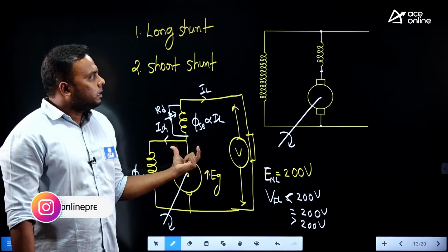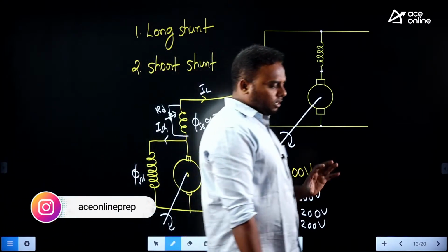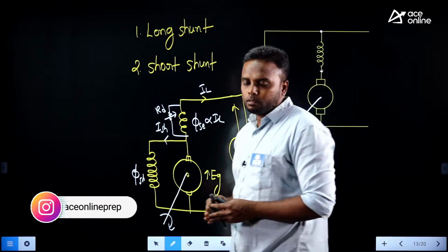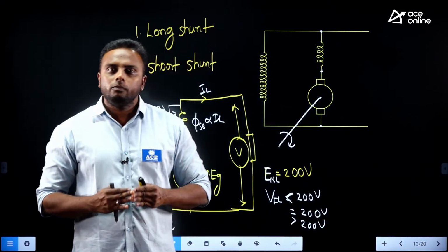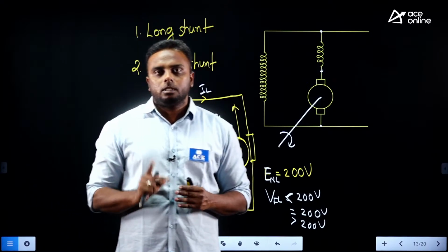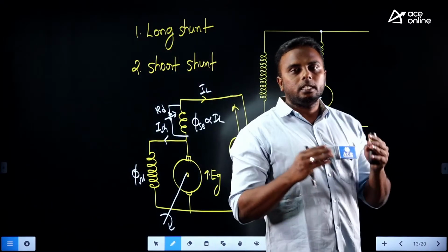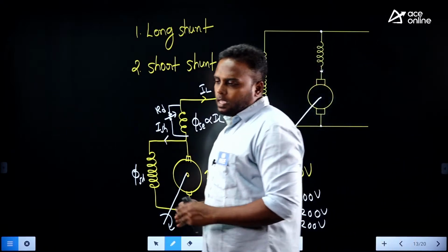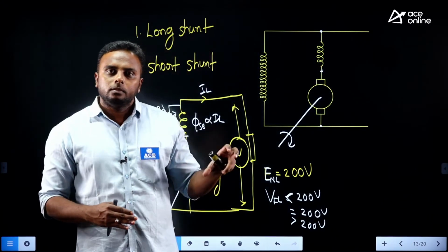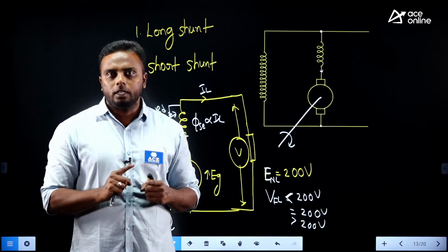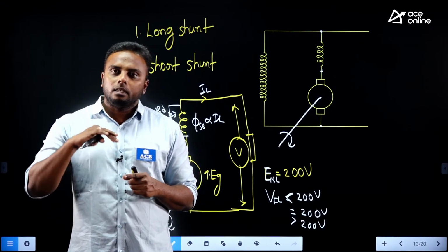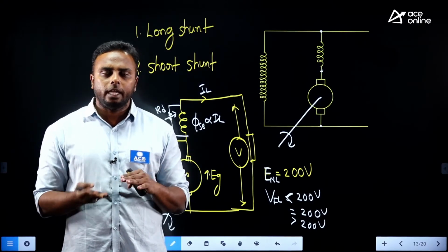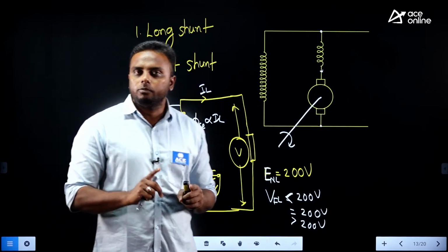Now these are the types of DC machine overall, a brief idea on how we divided them. Based on excitation of field winding we divided mainly two types, separately and self. Self is again divided into three types, shunt, series, compound. Compound is again divided into two types, mainly cumulative and differential, and again based on type of connection two types, long shunt and short shunt. Long shunt and short shunt are also out of cumulative and differential only.